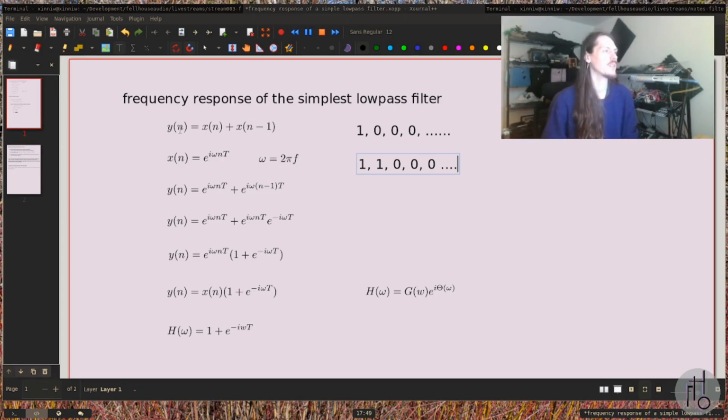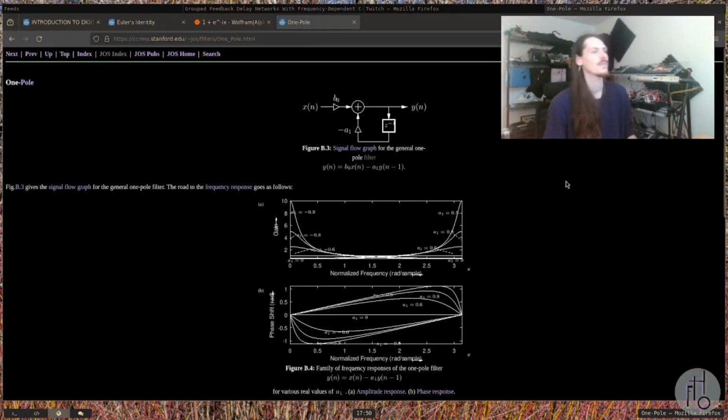If the filter operated on the prior outputs, we don't get a finite impulse response. And that's a little bit more like the filter that we talked about last week that we made our exponential envelope out of. So here's another filter equation. The current output is equal to the current input scaled by some constant number minus the last output scaled by some other number. This filter does not have a finite impulse response.